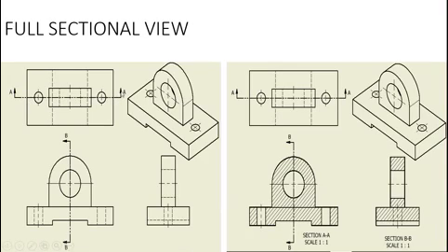So remember, they say that for the full sectional view, you cut the half of the drawing. So you can see that here they just cut the half of this drawing. So they just cut it at the midpoint. Similarly with section BB here, you can see that they just cut it here at the midpoint of this drawing. Okay, so when the question comes, it will look like this. Now we have to section this part. We have to cut section AA and also cut section BB.